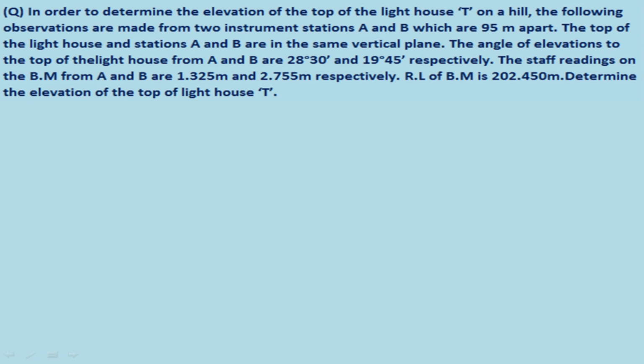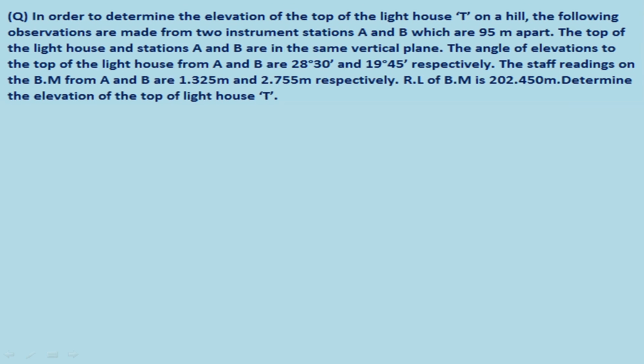The staff readings on the benchmark from A and B are 1.325 and 2.755 meters respectively. RL of benchmark is 202.450 meters. Determine the elevation of the top of lighthouse T. Draw the figure using the given data.